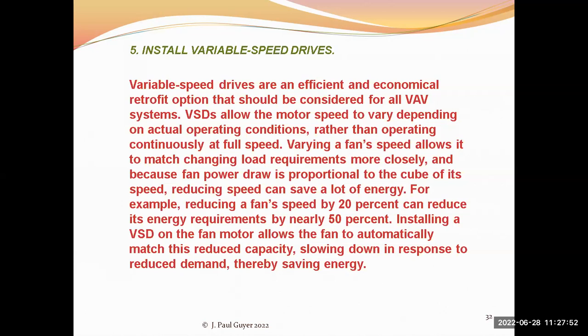So converting to a variable speed drive for the motor on the fan is a good opportunity to look at to conserve energy. As I previously indicated, the fan power draw is proportional to the cube of its speed. So reducing the speed can save a lot of energy.